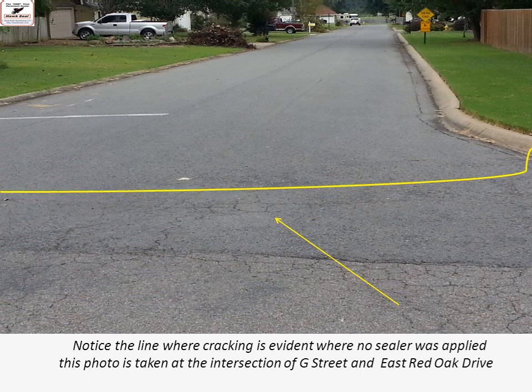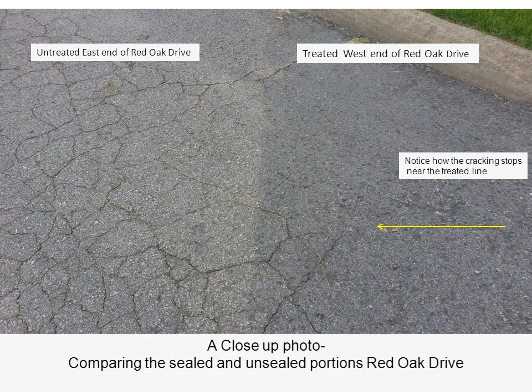This photo was taken at the intersection of G Street and East Red Oak Drive. You can see as Red Oak comes down here, kind of where that yellow line that I drew across there, on this close side of that line is the intersection of G Street, and you can see G Street's cracked up, and also you will notice that the untreated east end of Red Oak Drive shows a tremendous amount of cracking compared to the west end. And in this photo you notice how the cracking stops when it gets near that treated line.